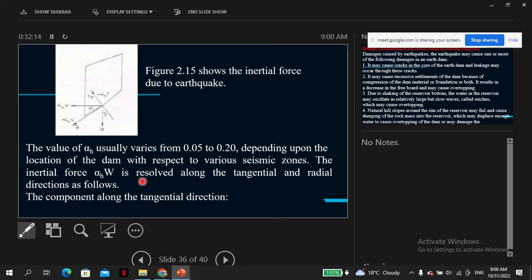When you are designing, you have to calculate the wind, and then the earthquake. You also have to consider the probability that an earthquake and wind will occur at the same time. Normally wind forces are higher than earthquake, because earthquake in this region is minor.